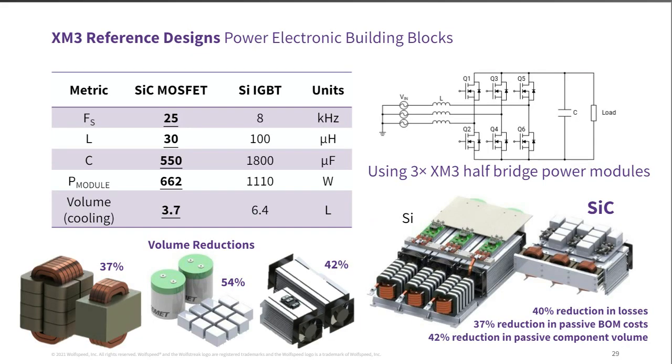And so from these XM3 reference designs, where we see these fitting in, we've done a previous webinar on an active front-end design. This particular design is air-cooled, but to make the comparison, really, again, with silicon carbide and our 1200 volt modules, a simple 2-level active front-end topology is achievable.